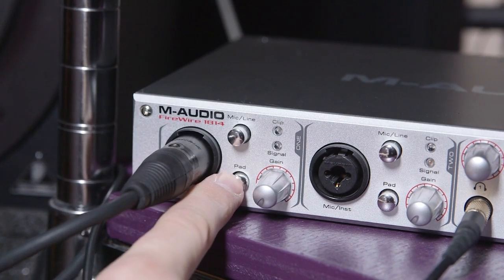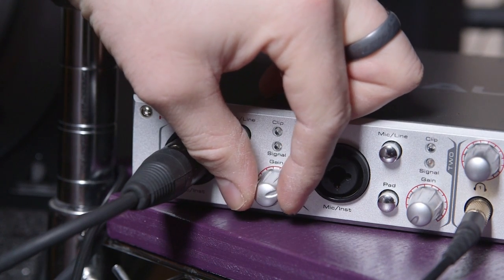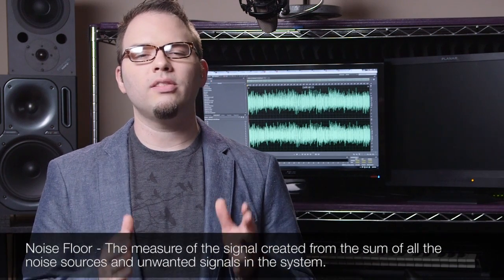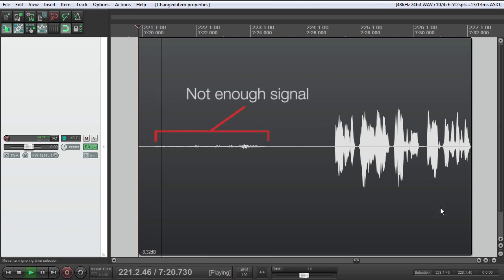Getting a good signal to noise also means setting appropriate levels on your preamp. If you have isolated yourself from external noise sources as best you can, there will still be noise in your recording. This comes from the AD conversion, the preamp, and even the microphone, and this is called the noise floor. The noise floor is the measure of the signal created from the sum of all the noise sources and unwanted signals within your system. If you set the recording level of your microphone too low, the level of your voice will be sitting much closer to the noise floor of your recording system. When you bring up the level in post-production, you will be bringing up all that noise as well.